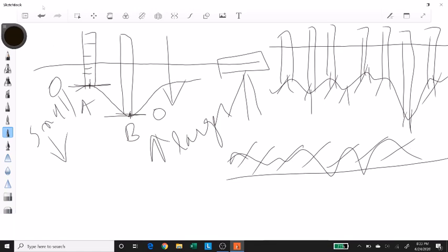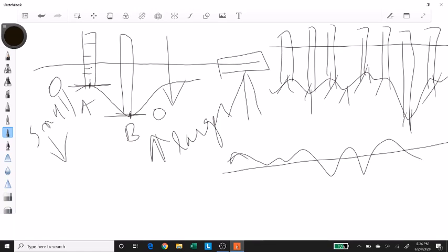So that's another cost. And another option is to select a profile in such a way that whatever soil or ground I excavate, I'll use the same one to fill it up where filling needs to be done. So that really economizes the project, and that is how you can use leveling as a very powerful tool to execute your projects.